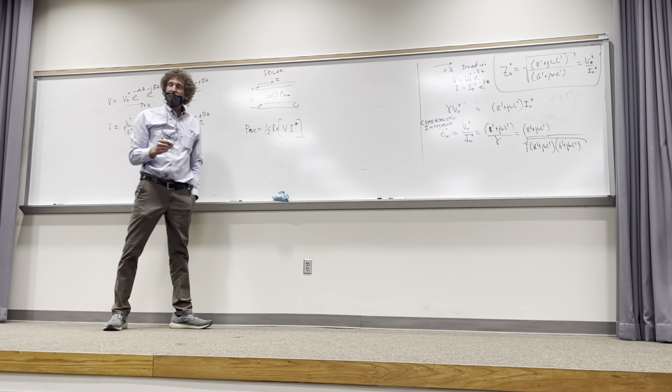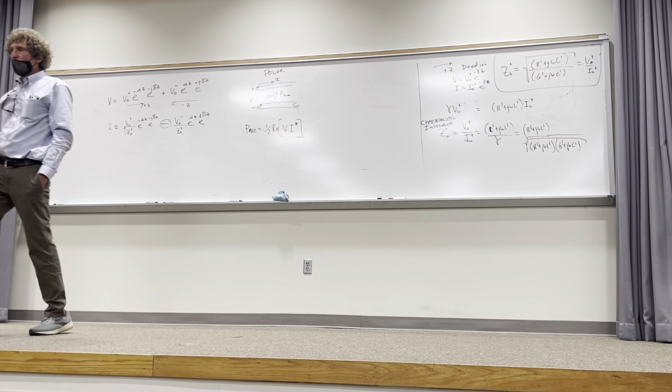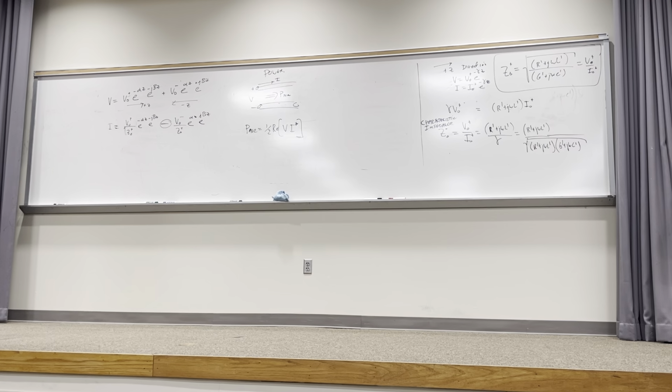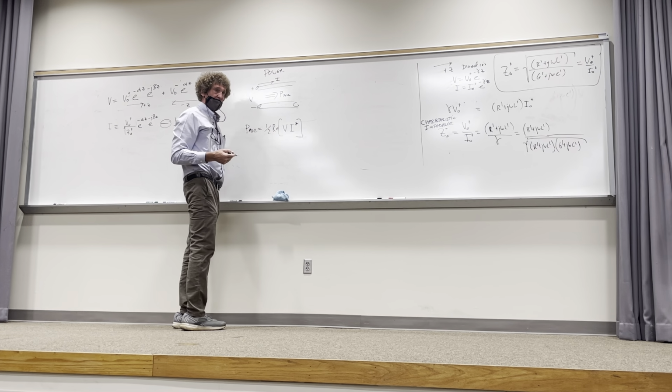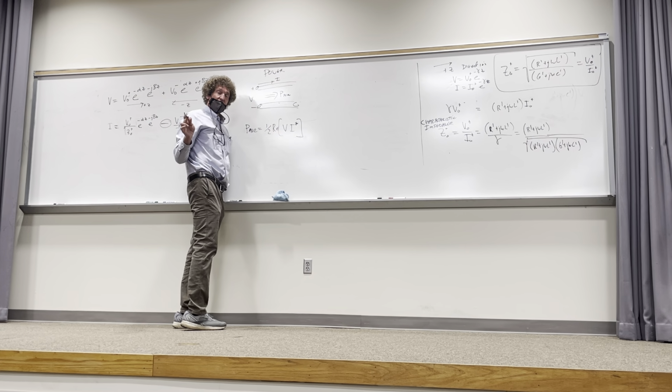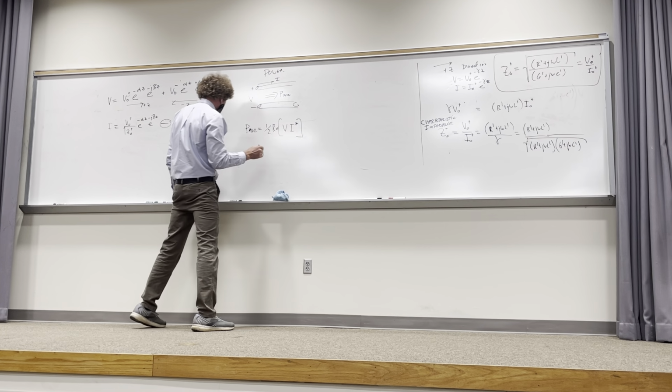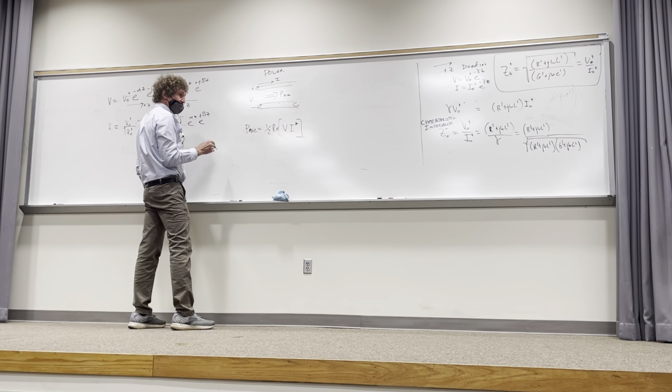Now, when you had circuits, do you remember how power was defined for DC things? It was just I squared R, V times I. There was not a half in there. Do y'all remember that? But here, because we're dealing with quantities where we're not using RMS values of voltage or current for I naught and V naught, what we have to do is include this 1/2. These are peak values, so it's 1/2 the real part of V times I conjugated. Are you with me?